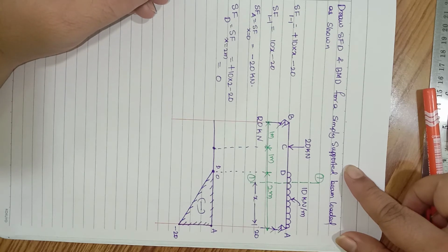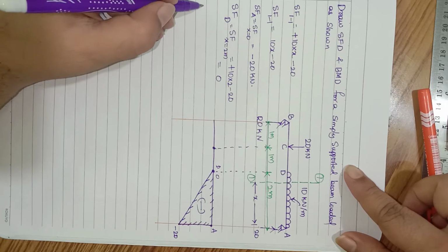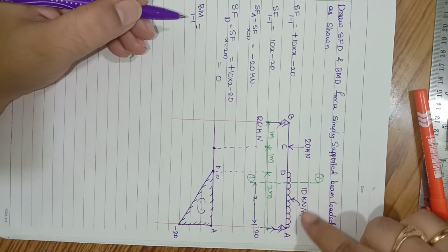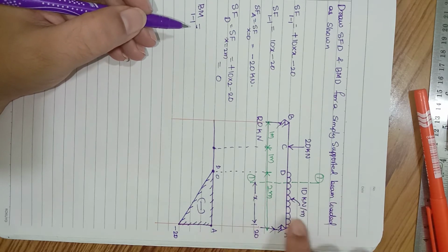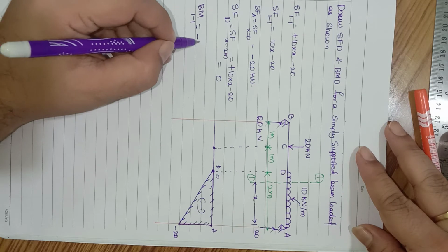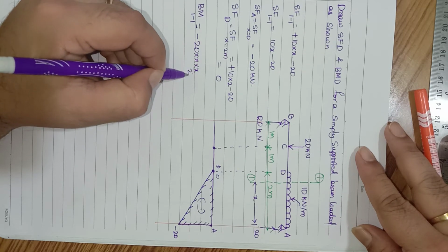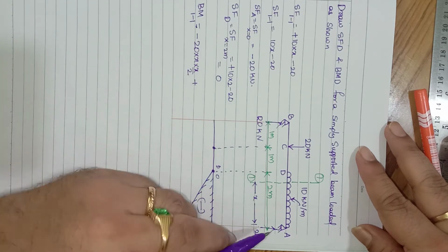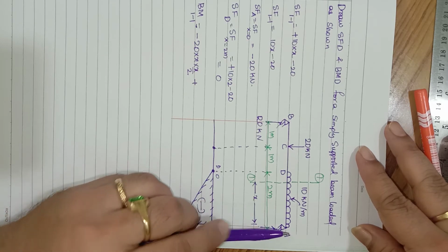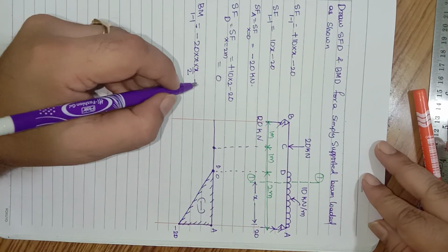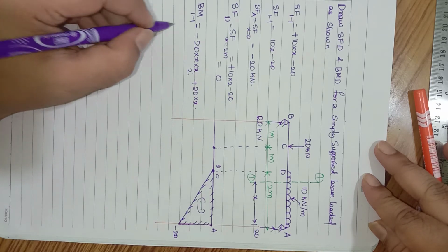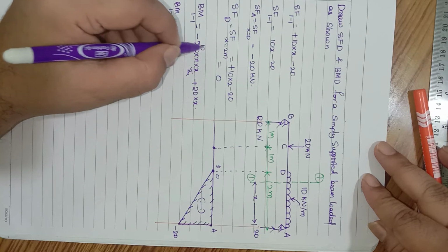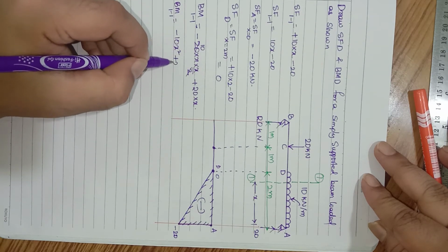Next, in the similar manner, let us calculate bending moment. Bending moment in between the section 1 and 1. So it is equal to, this 10 kilonewton per meter acting over a span of x will be pushing it in the downward direction, so it has to be taken as negative. Minus 20 into x by 2, the force multiplied by the perpendicular distance, x by 2. Next, 20 kilonewton is trying to push the beam in the upward direction, so it has to be taken as positive, as it is creating some positive bending moment. Plus 20 multiplied by x. So bending moment at any section 1 and 1 is equal to, it cancels for 10, minus 10x square plus 20x.